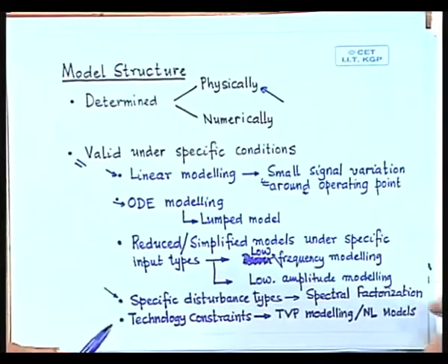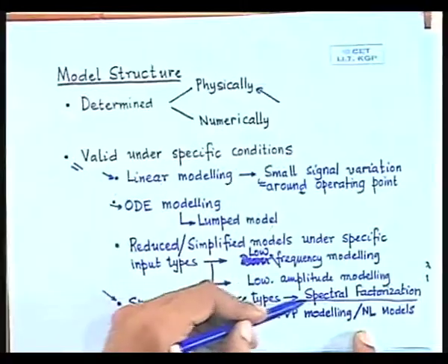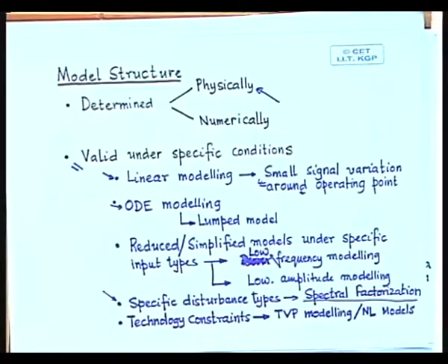Sometimes you will also have to construct and utilize models for disturbances, even for unmeasurable disturbances, right? For example, you have already done that in your Kalman filter. You have used a disturbance which is unmeasurable in your model. So how do you know that the disturbance acts like that? It will be that only if certain mathematical conditions hold, for example, only when the power spectrum of the disturbance can be spectrally factorized.